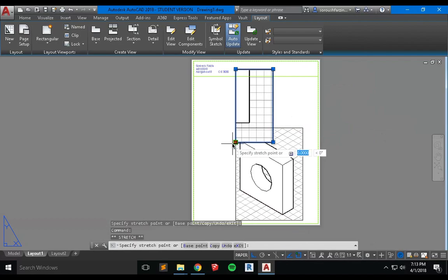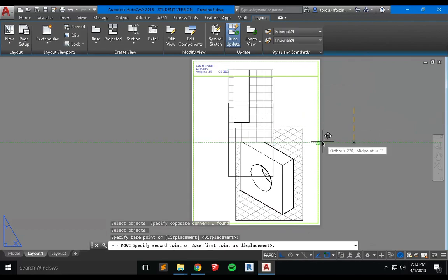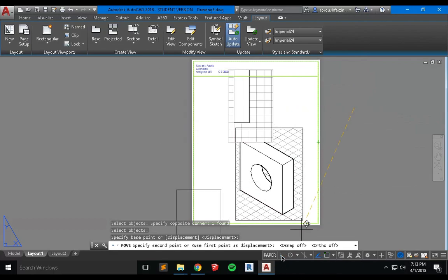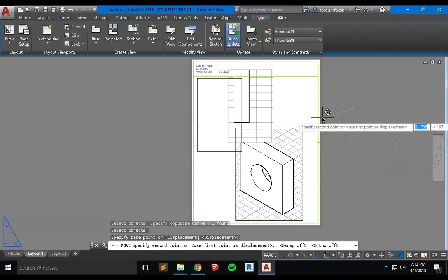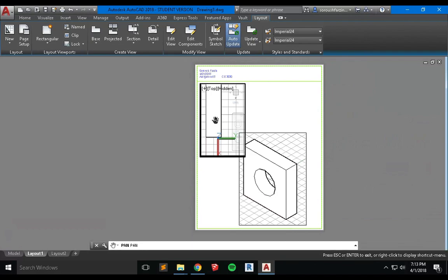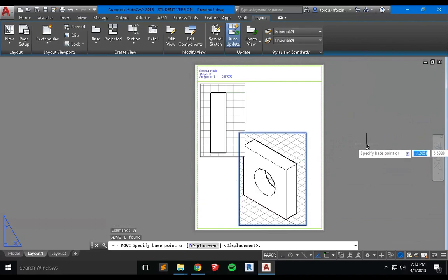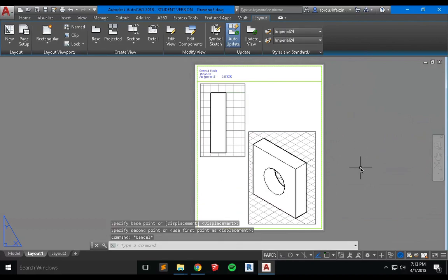1 scale, right? So all I need to do is adjust the placement of this viewport, place it in the right place. I'm going to turn off this object snap, turn on the ortho as well, so I have more control around the placement. Okay, and double click here using pan, and then bring it over here. Let's pull this one to the other side. So this basically is going to be one view.